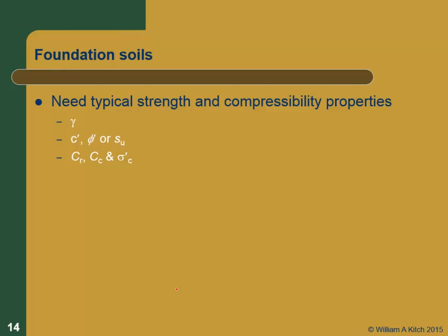If it's a relatively compressible clay soil, or if it's a fairly stiff soil, you're probably better off estimating settlements using elastic methods and just getting a Poisson's ratio and a modulus of elasticity or some other modulus method, and just calculate the settlements based on elastic methods. For those of you in 531, we just had a big discussion about that last quarter.